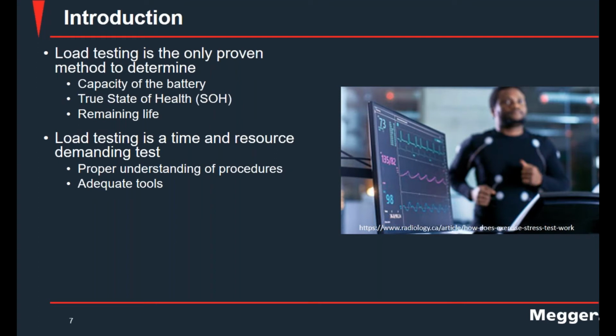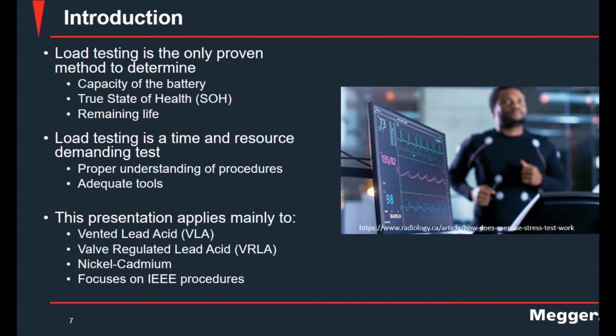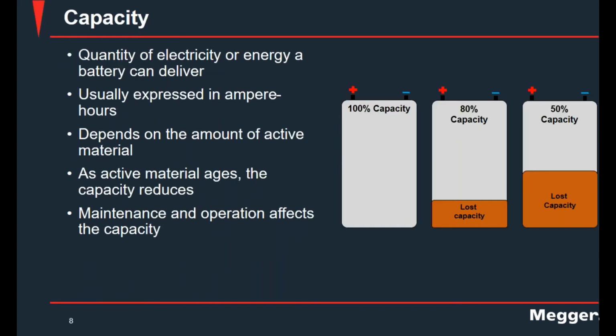Despite being the main test that you can perform, it's really a test that is load, resource and time demanding. You need to have a very good understanding of the procedures and use the adequate tools to run the test. So that's why we're presenting all of this information. And we're going to focus mainly on vented lead acid batteries, VLA, valve regulated lead acid batteries, VRLAs, and nickel cadmium batteries, and all of this is related to IEEE procedures.